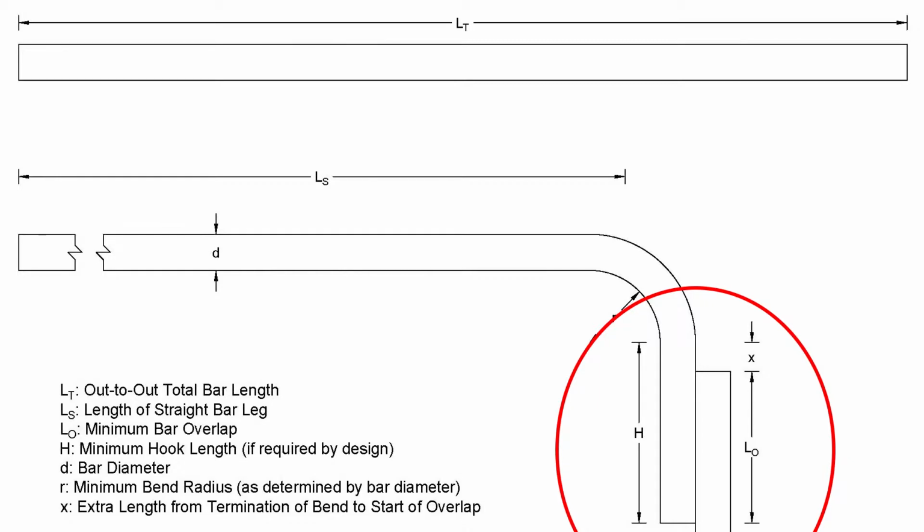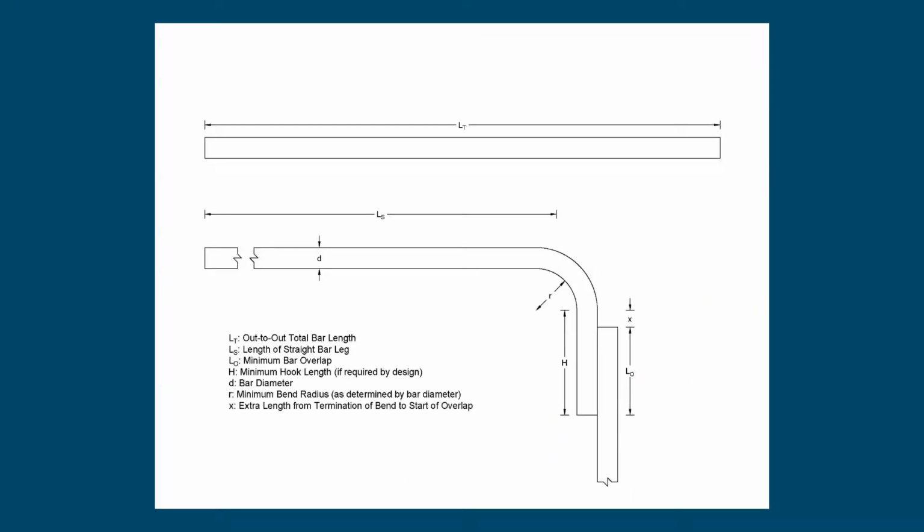Lastly, when determining the total length of the bent steel bar or mat, the final length of the bent leg also needs to be determined and included. If the bent section is a continuation of the tensile steel with the required lap of another section of reinforcement, the minimum length of the bent leg is needed to get that satisfactory overlap splice.